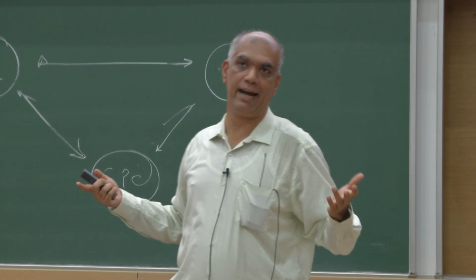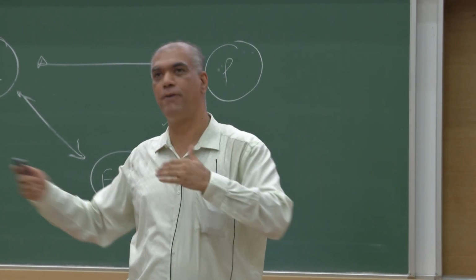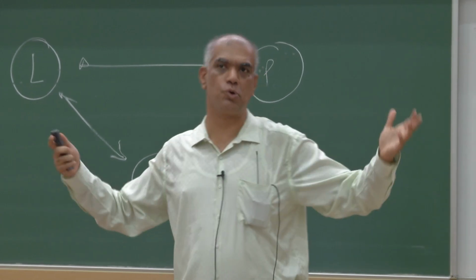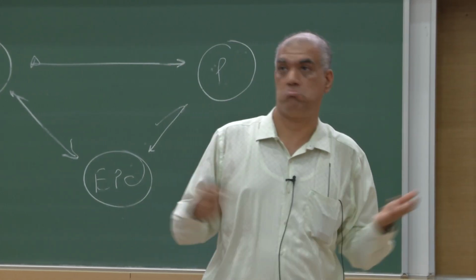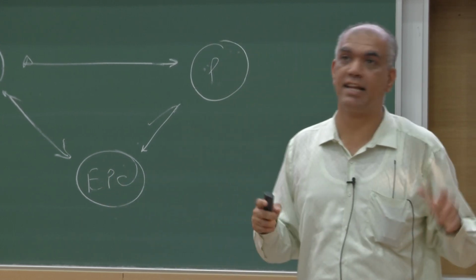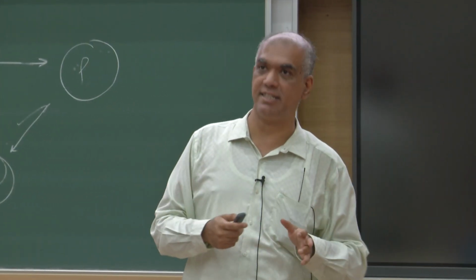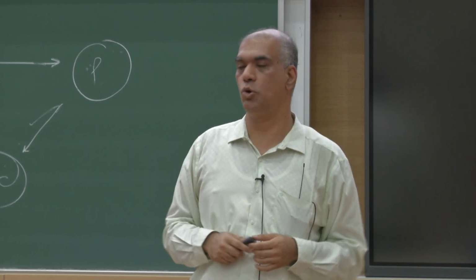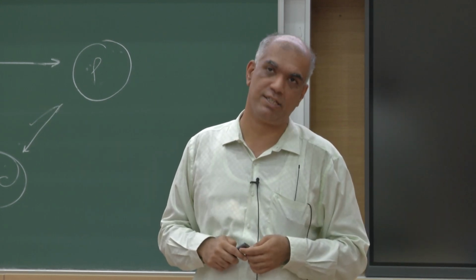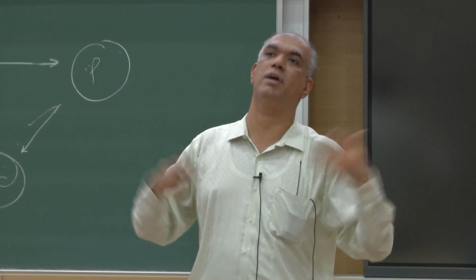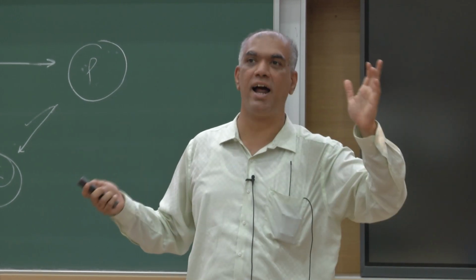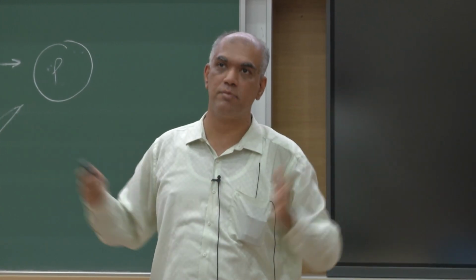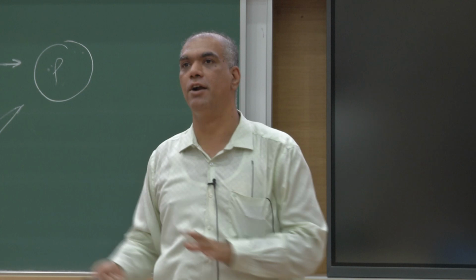What's the point behind a layout? To know how far you should keep things. Suppose you have a very high temperature reactor. Do you want a storage tank right next to it? No, right? A high temperature, high pressure reactor is likely to have an incident. Suppose there is an incident and a small fire. If you have a very large 200,000 liter storage tank right next to it, then even a small incident will become a big one. And if you have visited plants, you have seen how the Reliance tank farm was far away. That's why tank farms are far away. So that comes in the part of a layout.